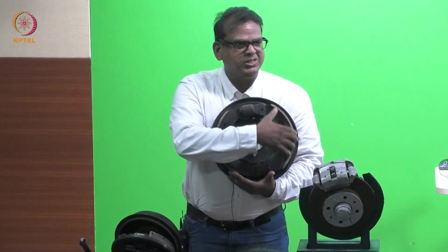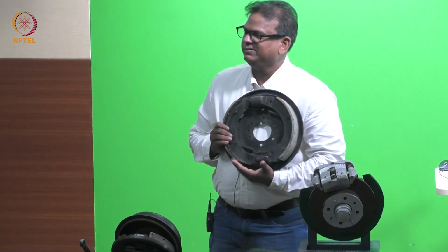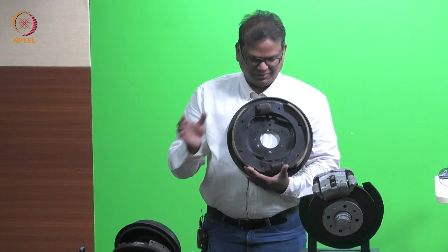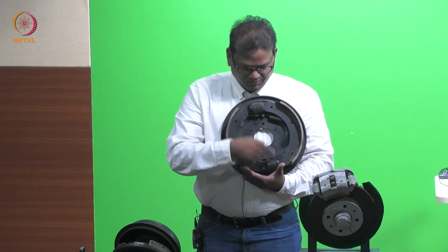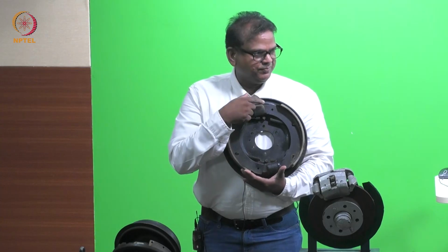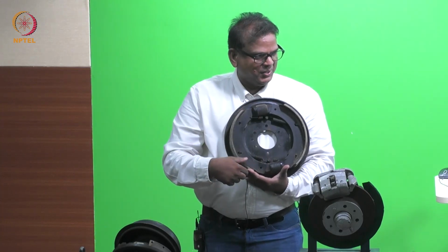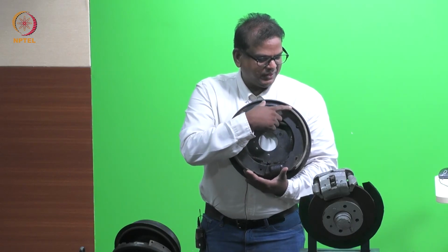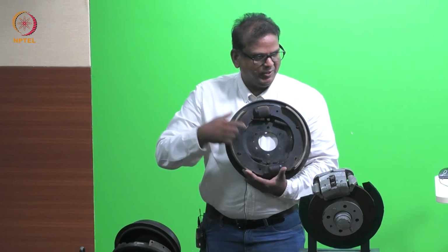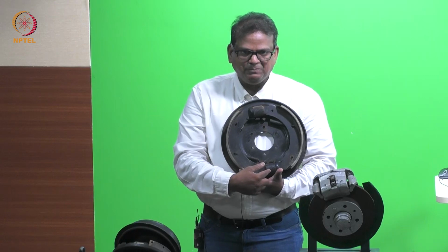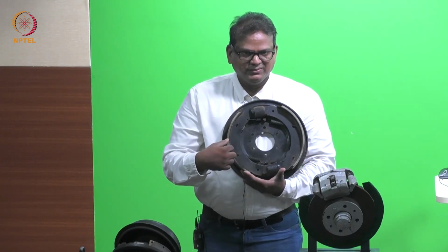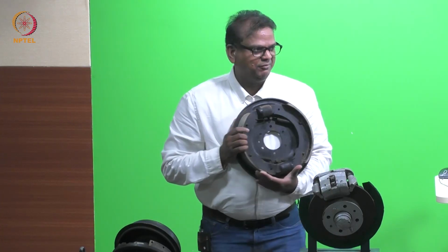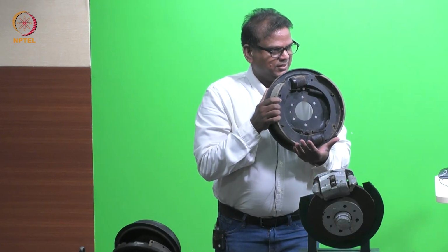In fact, this arrangement is called leading brake shoe. We will discuss what we mean by leading. Generally you will have a leading and a trailing shoe, but since you have two cylinders, given force, both will activate. Whereas earlier, if you have one cylinder alone, one shoe will be used for the same direction of rotation, the other for the opposite direction. If you have another cylinder, both will have the same direction of the drum, so it will be much easier to stop the vehicle. That's the reason to have a leading shoe brake system.